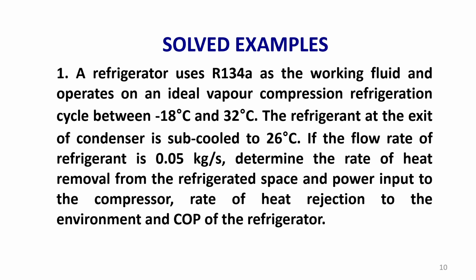There may be some time constraint because 3 methods are employed. Some of the enthalpy will remain the same. If it is subcooling, the H3 value will be changed to H3 dash. When H3 is changed, obviously H3 dash will be equal to H4 dash. When we have superheating, state point 1 dash is moving to state point 1. So, the enthalpy and entropy values will change corresponding to state point 1.